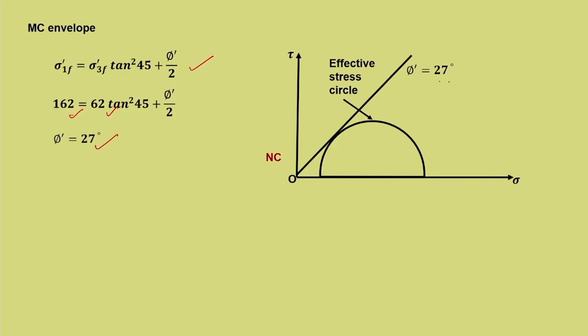and that is plotted as follows, and this is the bound. This particular line is the bound. Now, only one Mohr circle is there. If you have 3 Mohr circles, as we do for triaxial testing, an average line which is tangential to the 3 Mohr circles gives the failure bound, or Mohr Coulomb failure envelope.